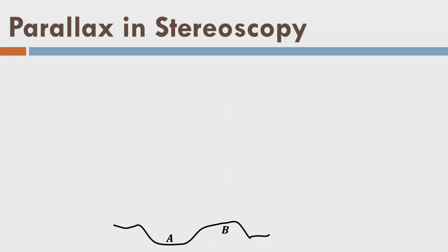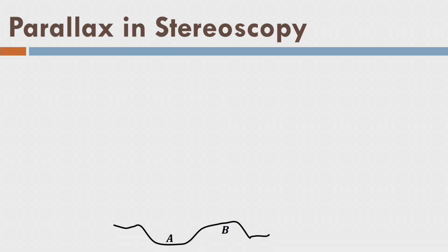And so, let us see that we have acquired the photographs. That means by flight planning I have decided that yes, this mission is worth it. That means I am going to create the 3D view of the terrain, and that is going to have enough impact, in a sense like this cost is justified. And so, let us go for the data acquisition. Once I acquire the data, that series of vertical photographs having some end lap and side lap, I want to create the 3D using parallax. So, let us learn what is the parallax again in terms of aerial photogrammetry.